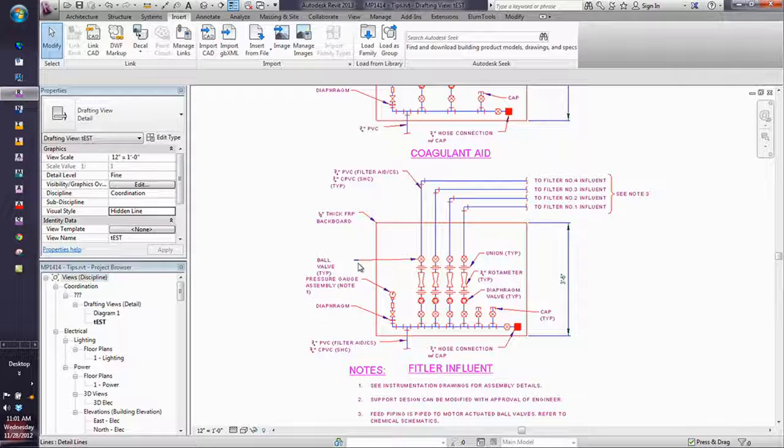Do you replace them with that? If it's a detail that I'm going to use, then yes. Absolutely. What we started doing is that when we started getting a bunch of details that were always going to be used in Revit, we would import them like this, but we would blow the text away and the leaders and redo them. We found that was a whole lot easier to do. We left them in there as a reference so they would know what to put, but once they got them in there, we just had all that stuff replaced.